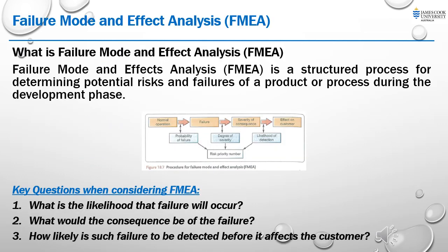Failure mode and effects analysis is a structured approach used to identify and analyze potential failures in a system, process, product, or service, and their potential effects. The purpose of failure mode and effects analysis is to anticipate potential failures and take corrective action to prevent or mitigate them before they occur. It is a proactive risk management tool that helps organizations identify and prioritize the most critical risks and take action to minimize the impact.